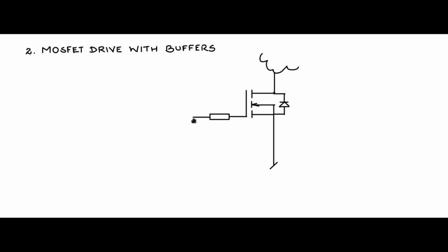Now here you apply the gate drive pulse in the normal one resistor gate drive. When you apply the gate drive pulse, you have the charge being pumped into the gate, and the MOSFET turns on. But the turn on time is decided by the amount of Ig plus that can be drawn at that given instant of turn on, and that is dependent on the sourcing capability of the source.